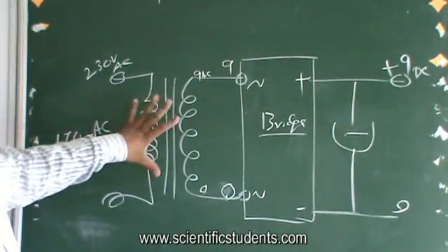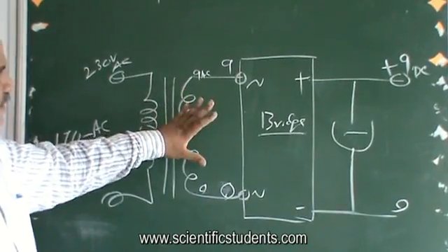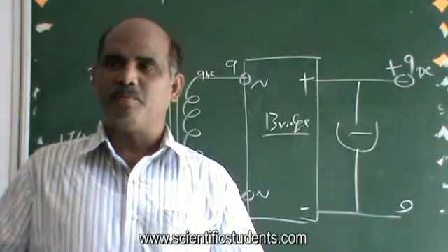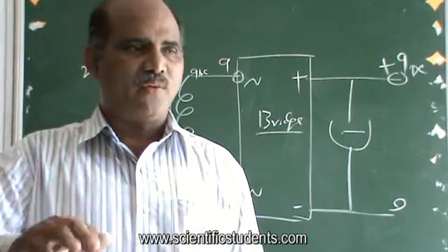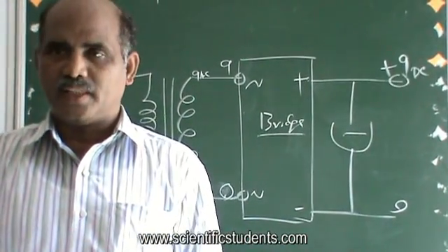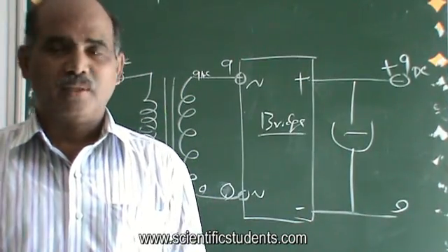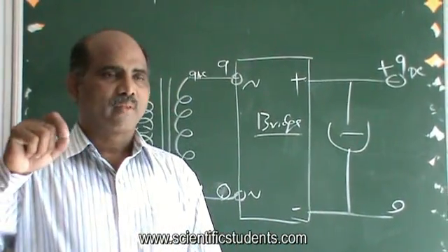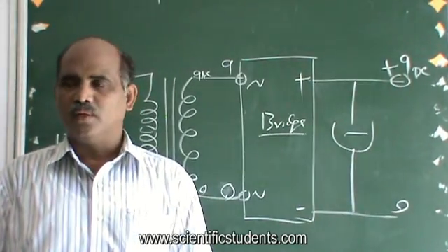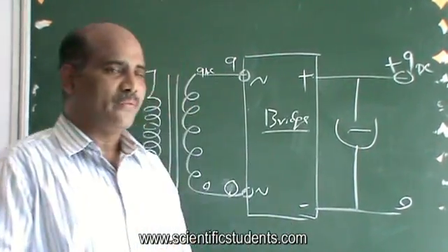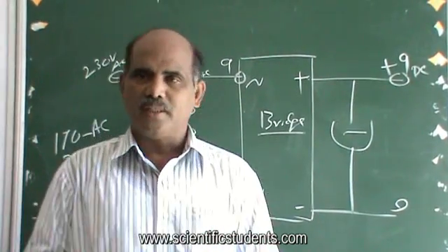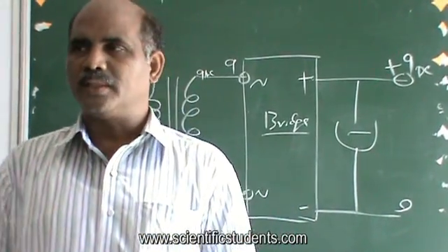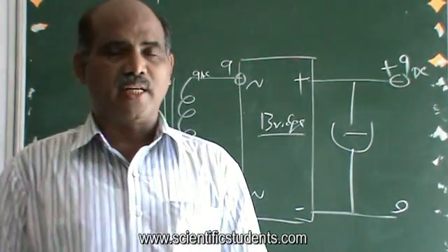Because of which the secondary voltages are also varying, because of which the DC voltages are also varying. So your circuits may not function properly, because they are designed for well-regulated, constant voltages, since they are all electronics. We have designed them to particular reference voltages. There are so many reference voltages. So if the reference voltage is varying, the functionality of the circuit is varying, so ultimately the output of the circuit is varying. The performance is mismatching. A lot of dangerous things can happen.